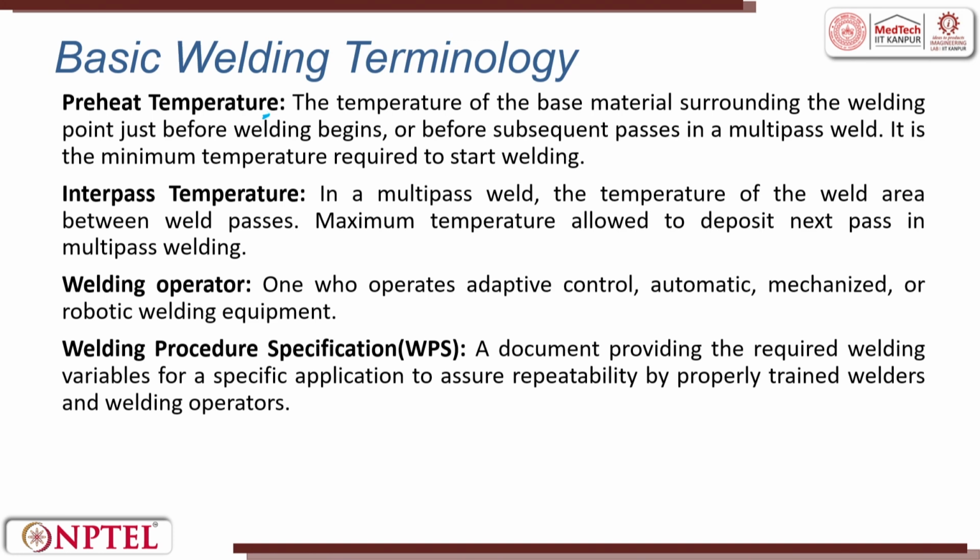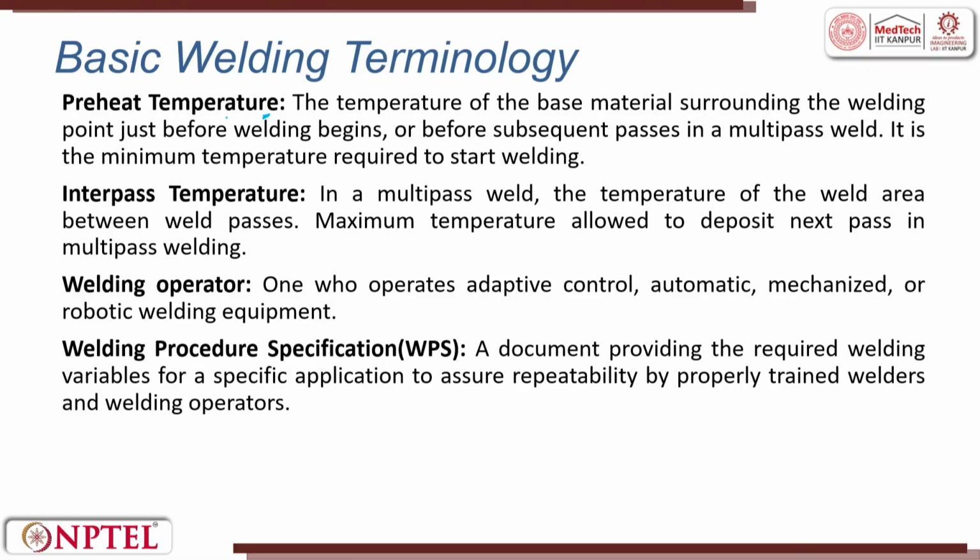Going directly from 0 to a higher temperature while welding happens is a sudden change in the gradient, which can lead to expansion or contraction of metal, which can lead to cracks. So, preheating is required. Basically, we take it to 0.3 times, 0.4 times or even 0.5 times, wherein we try to release the residual stresses and expand the grains a little bit before the welding happens. So, preheating temperature is very important.